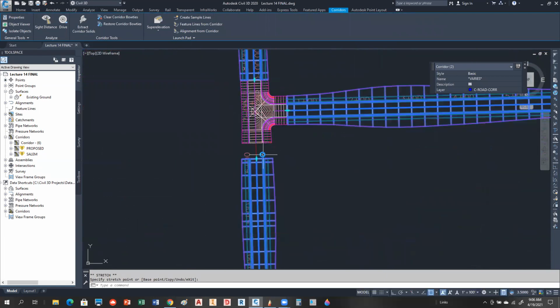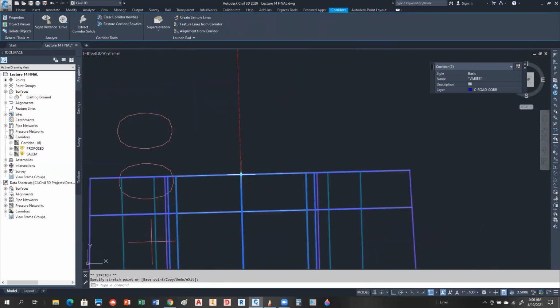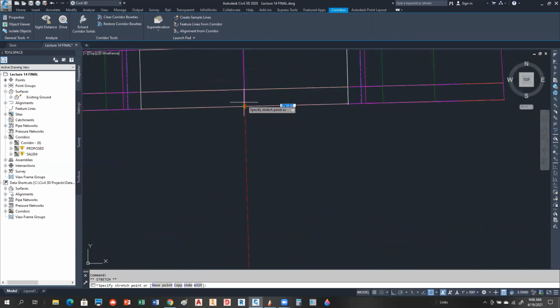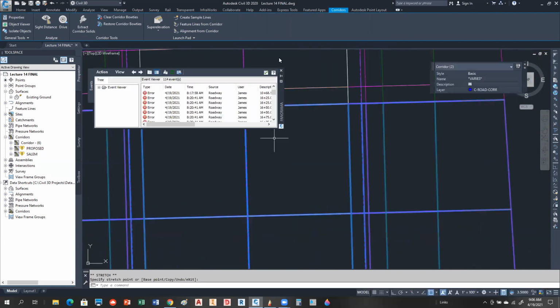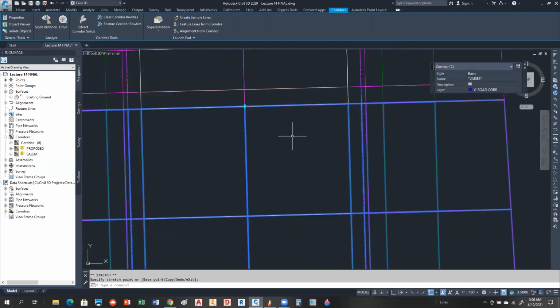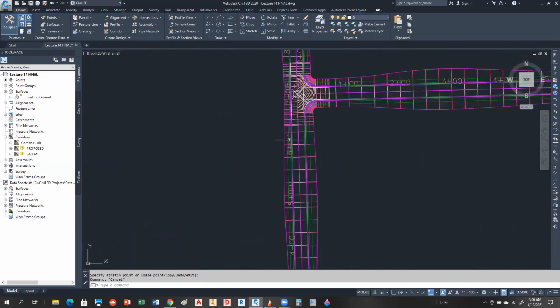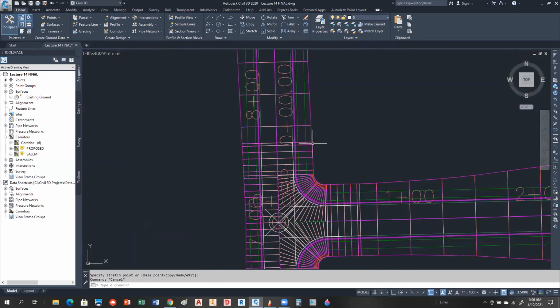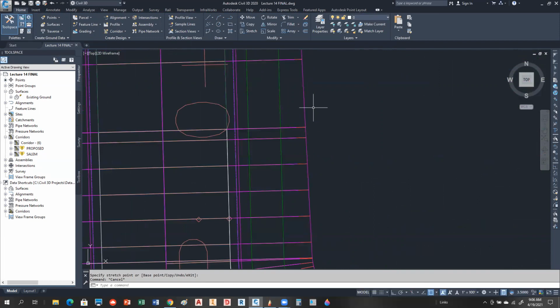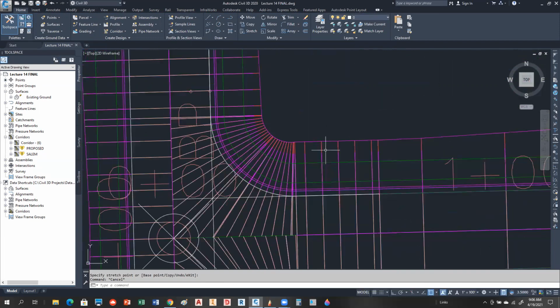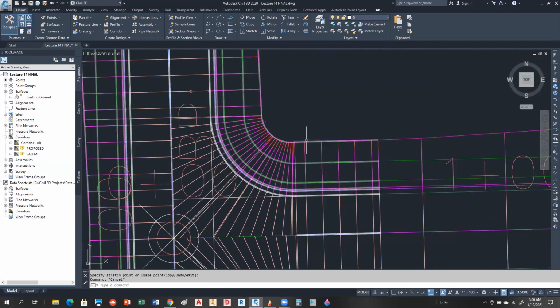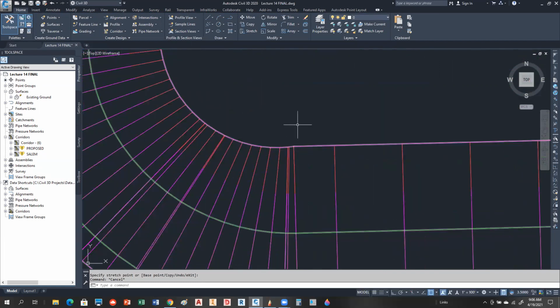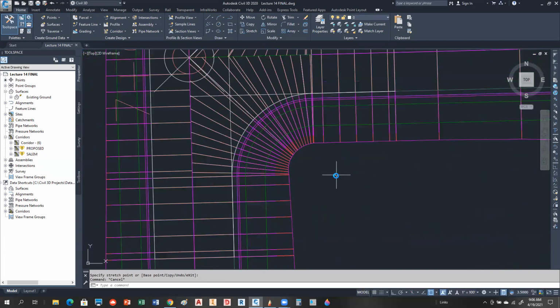So I want to do the same thing here. Go from this guy, just change that region up to that endpoint. Don't worry about the error messages. They pretty much always occur. Now what's important to look at is make sure the daylight lines are hitting. They're hitting there. That's all hitting. By the way, this usually never does this perfectly. You can see a little bump there. This has really modeled it well.